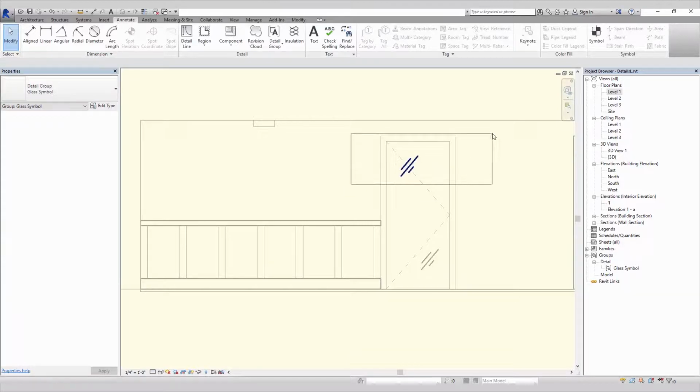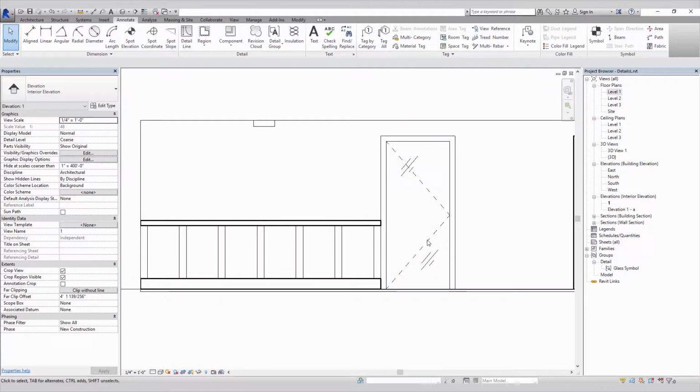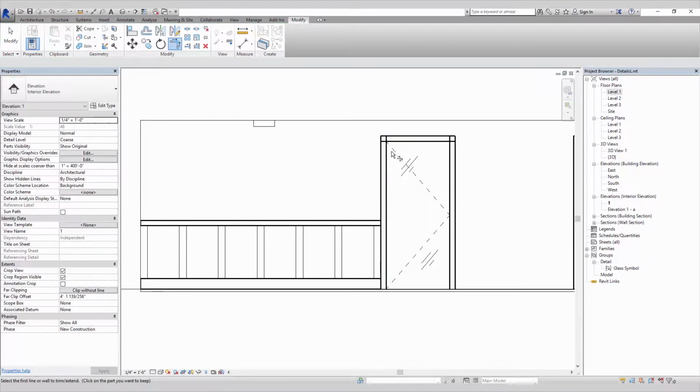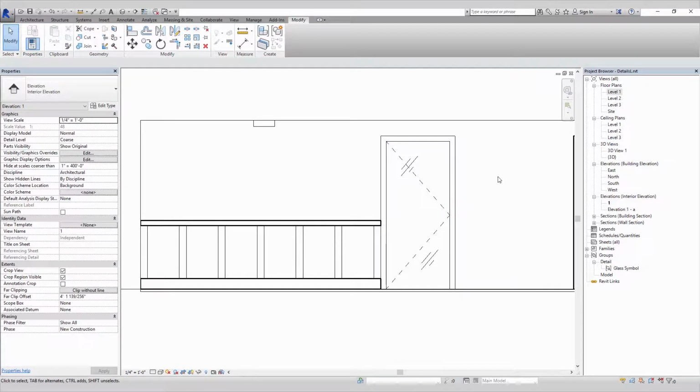For detail lines, you can of course change your line weights. Those should be thin for sure. Hit OK, and that thin those out. And again, for the modeled objects, a lot of people I know will use the pick tool and draw over your existing objects. While that is one method, that is not the most efficient method. A great tool to use to control your line weights is this tool right here, the line work tool.